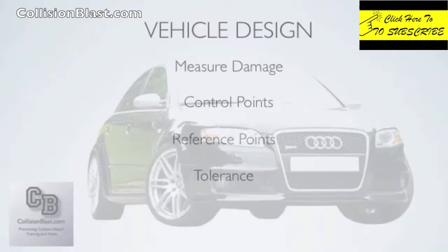Now reference points are what you're going to use when you go to measure the damage. It could be a control point from the factory, it could be a hole, but it could also be a bolt or just anything that they reference as a point. So whenever you look at the specifications, it's going to give you references. From this bolt to that bolt should be 33 millimeters or whatever. So that's what a reference point is.